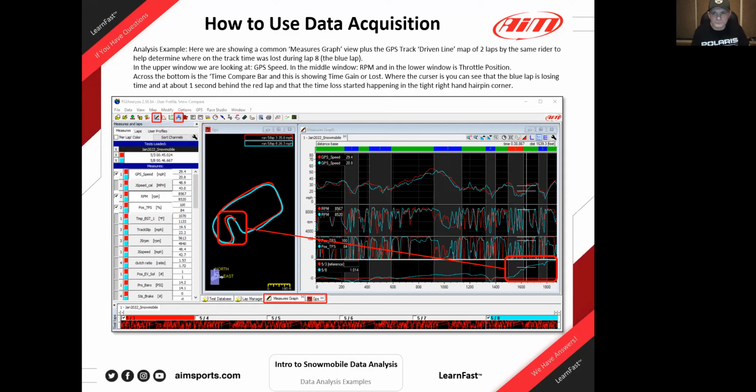Where did it happen? It all happened right here, and I clicked the cursor there for this picture, and you can see these are dynamically linked together, right? So wherever I put this cursor, the cursor of the 2 laps shows up over here in the GPS map. This big red box will not be there when we look at the live data, but right there, it's halfway through the loss, right? All of that blue lap being slower happened on this hairpin and taking that inside corner. Could not get back to the throttle as much and lost a bunch of time, all the way through this entire section. And all of that happened in this hairpin.